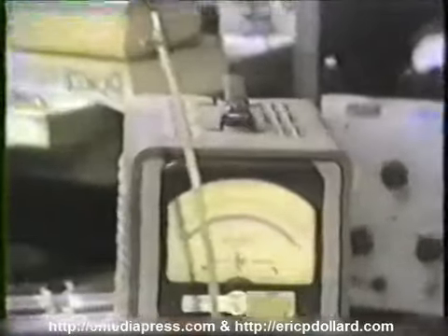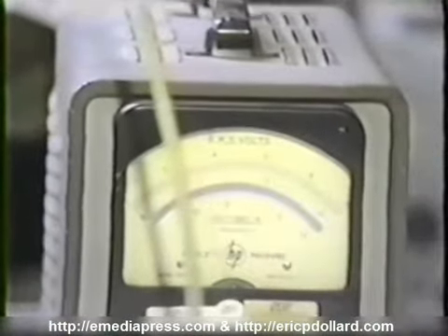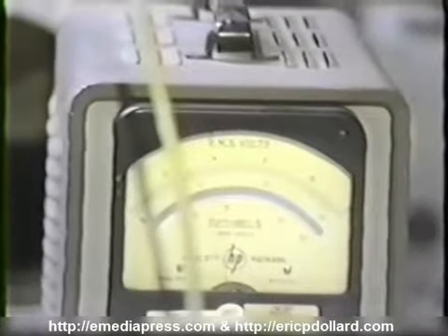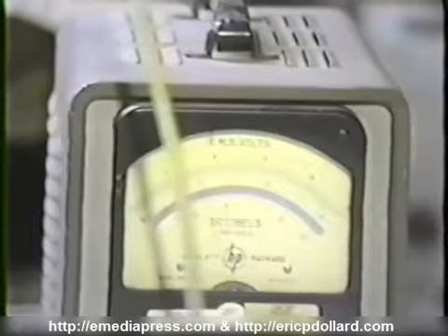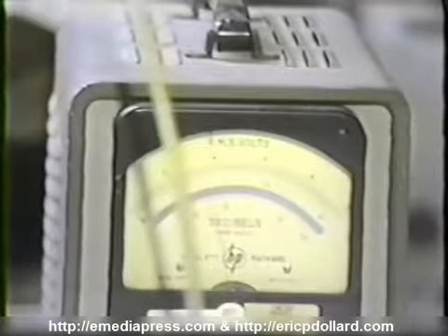Now we notice a difference right away. The resonance of this type of wave is much sharper. Rather than varying over several hundred kilocycles, now I'm varying over several kilocycles. So we're talking about a sharpness factor, or a Q, of 100 times greater.